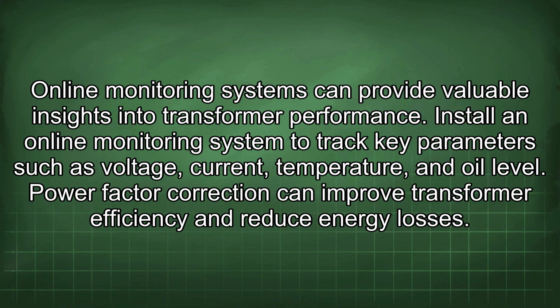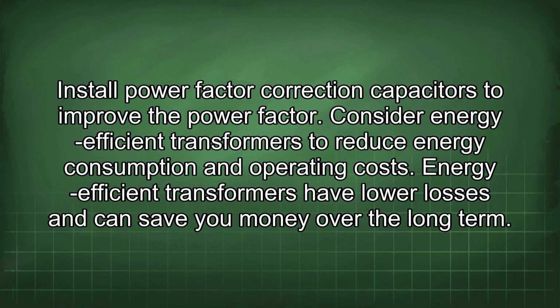Online monitoring systems can provide valuable insights into transformer performance. Install an online monitoring system to track key parameters such as voltage, current, temperature, and oil level. Power factor correction can improve transformer efficiency and reduce energy losses. Install power factor correction capacitors to improve the power factor.